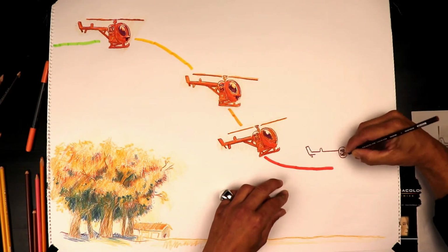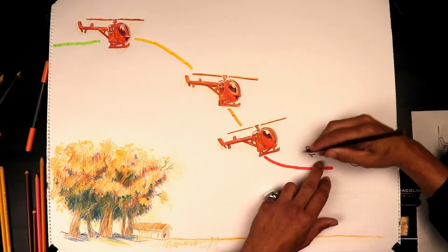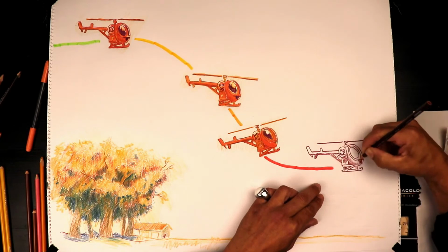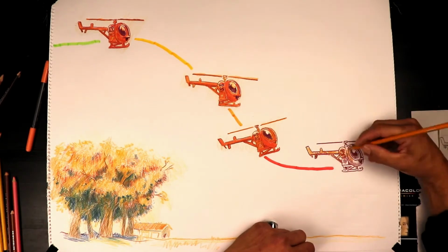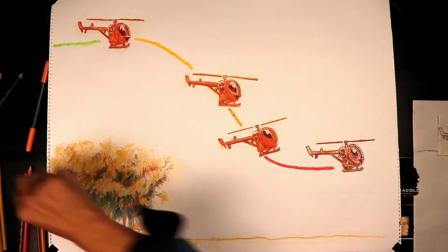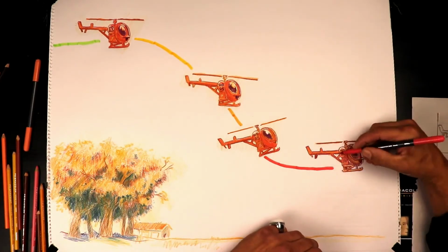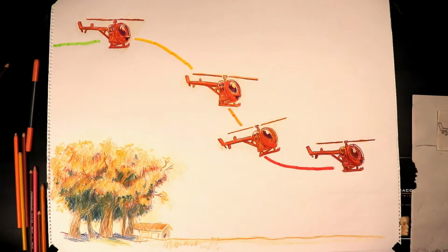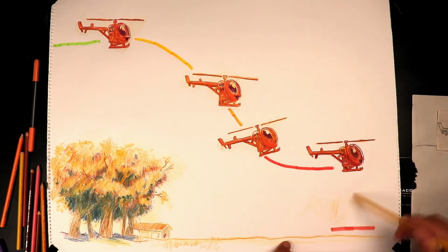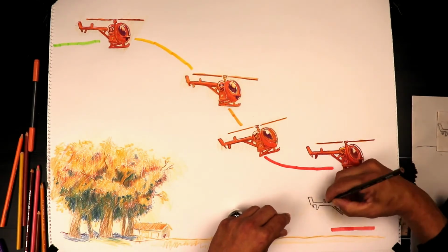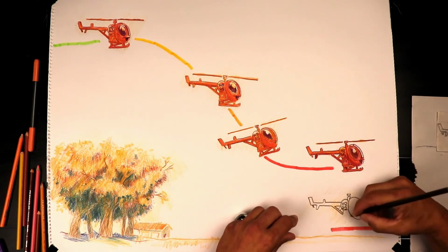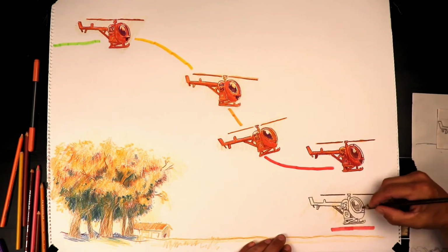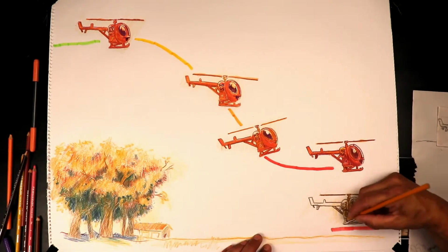Okay, so we had to give way for an airplane, so we're going to cover another slide here as Gary is getting set up for the auto rotation. So you're going to have some type of a freewheeling unit, no matter what aircraft you're flying. Different models have maybe different names or a different setup, but basically I think of it like a clutch in a car, right? If you're driving a manual shift, you push the clutch in, the engine and transmission are no longer married. So in a helicopter, same thing. When we enter auto rotation, it's like pushing on the clutch. The main rotor transmission is then no longer driving the rotor system.